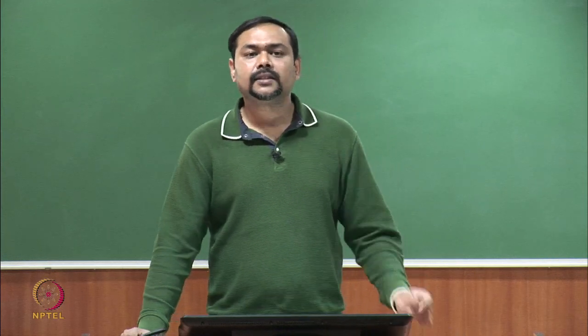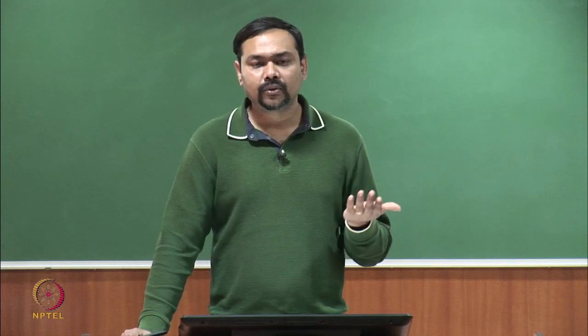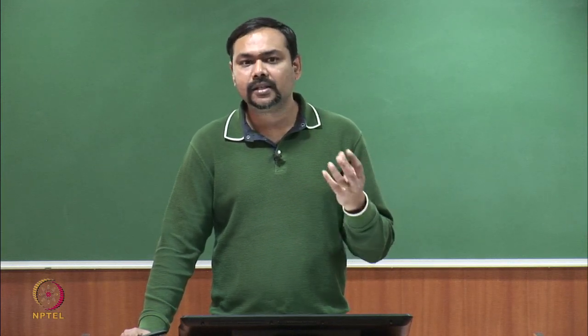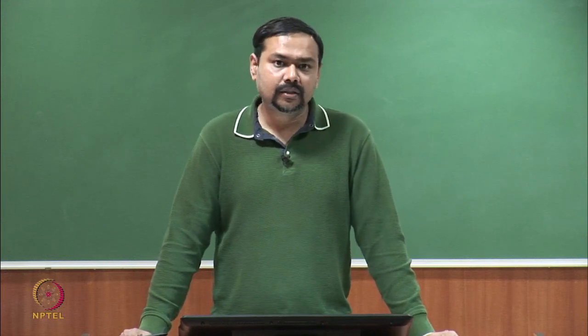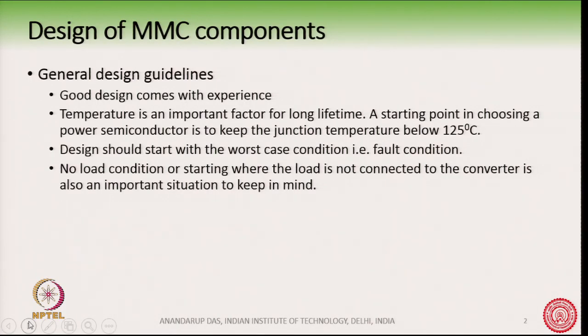Often we do not get the same value of efficiency from no load to full load. So, we then choose that the efficiency should be highest near the rated operation of the converter. No load condition is also something to be kept in mind, because in a no load condition the load has been thrown off the converter. How the converter will behave in the absence of a load is an important factor to be kept in mind.